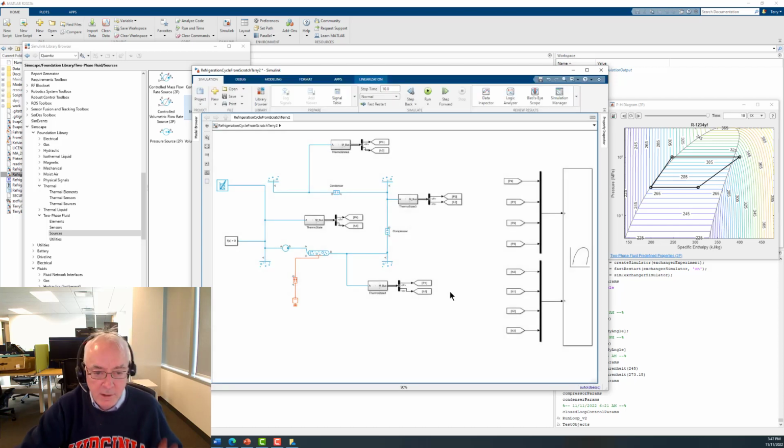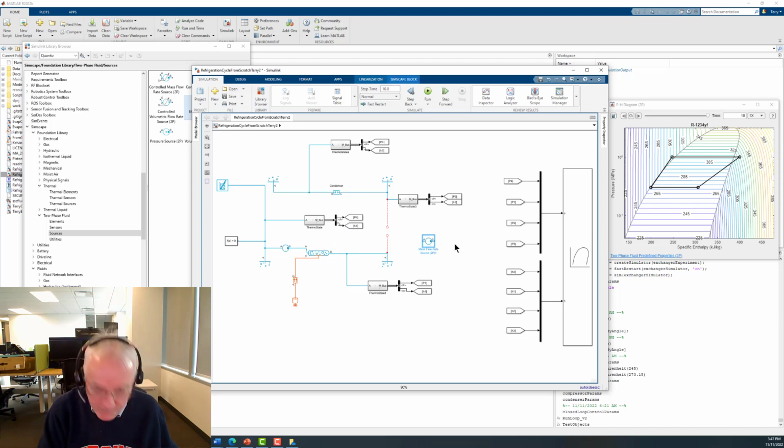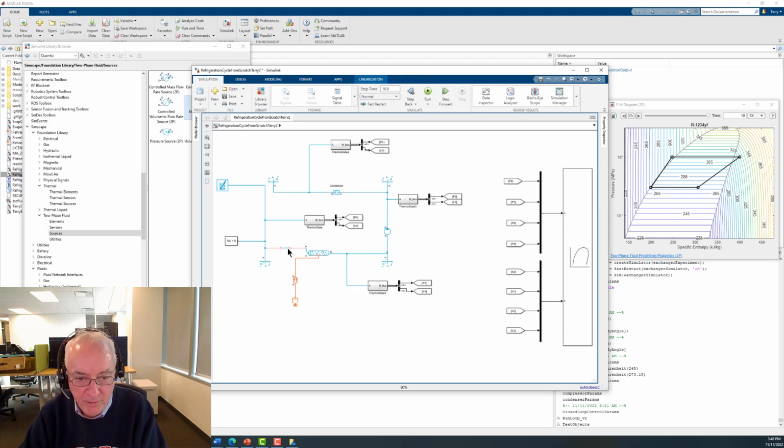So anyways, let's put that in and again, just assess where we are. Okay, I'm kind of happy the model runs. And what I want to do now is really think about, well, what's an evaporator and what's a compressor? Putting in this mass flow rate source, I actually practiced this like 4 or 5 times before I really began to think about it. Well, that itself is a kind of compressor. And so what I'm going to do is rotate that like that. And so instead of pushing the fluid through the pipe, we're going to pull it.